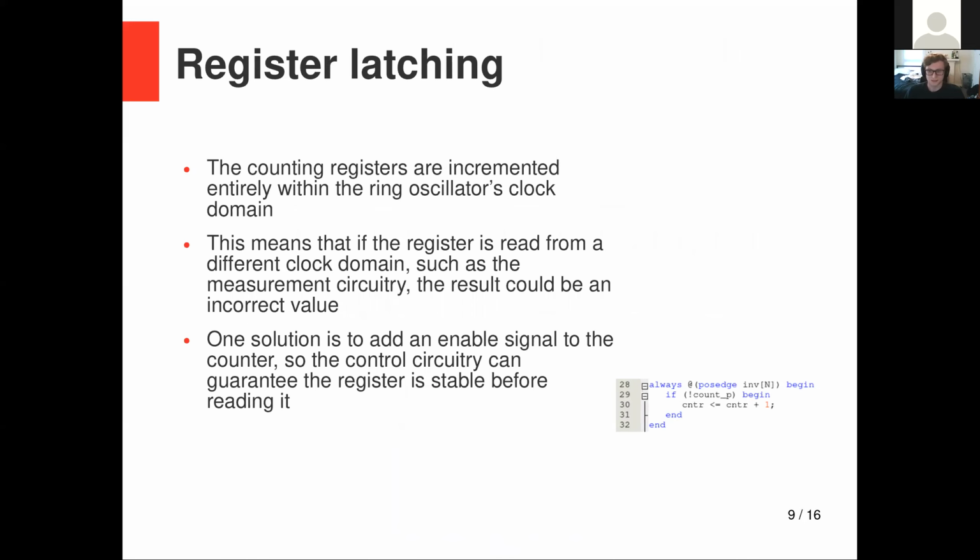Okay, so the register latching issue. As I said, the solution mainly was to put a little check in there. We had a signal we could send to it, and it wouldn't increment that counter unless we told it it could. So then we get rid of that signal, and then we can read out the counter with no worries about the collision.